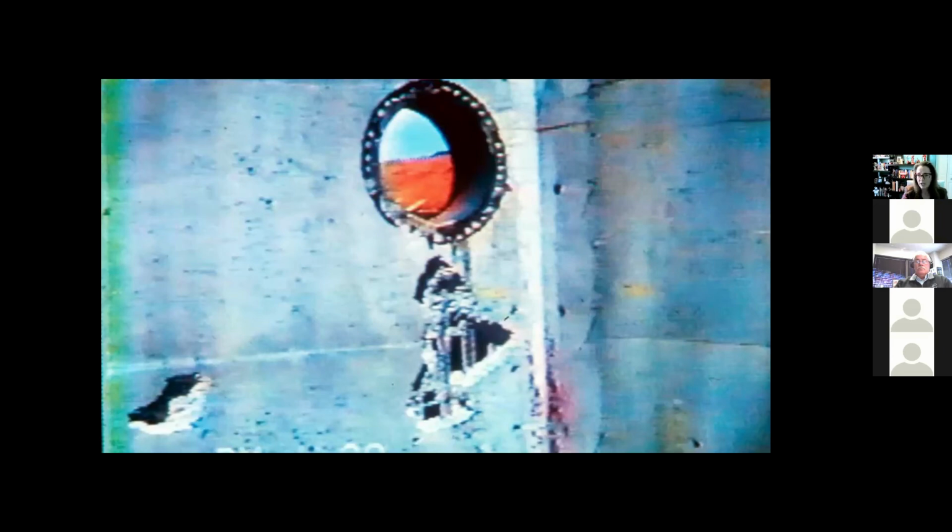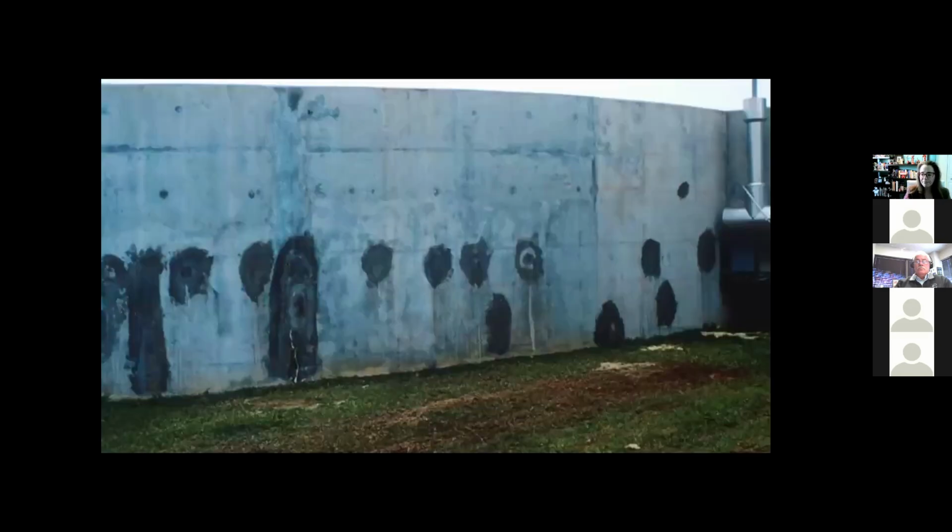So what you would do here is you would patch it, and that would mean not just parging and slapping concrete into that hole, but actually cutting out the deterioration and making sure you have a uniform shape so that you don't get shrinkage away as you're patching. And there's great guidance for you in the International Concrete Repair Institute's patching guides and in that Corps' manual of repair, which I highly encourage you to get.